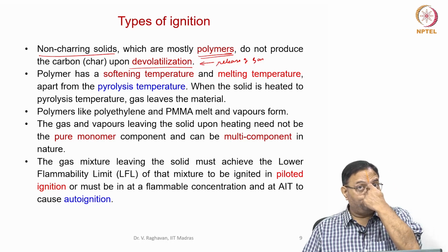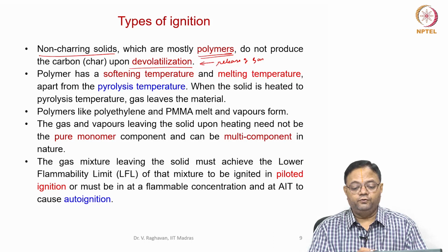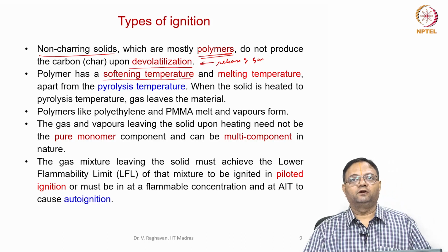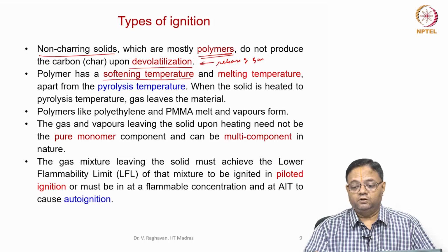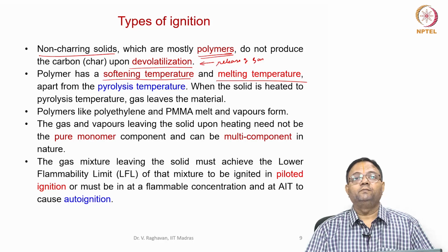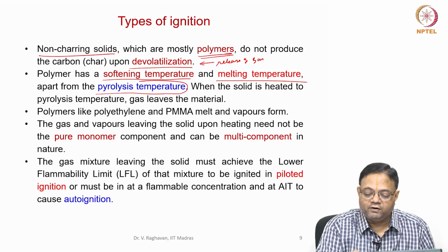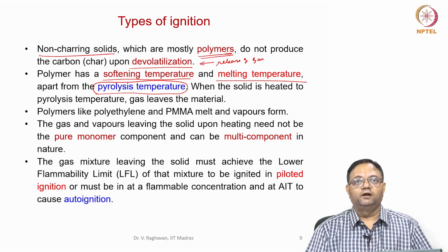Now when you do this heating of the non-charring fuel, there is a temperature called the softening temperature. A rigid plastic can soften. It can melt when it reaches the melting temperature. Now please see that the pyrolysis temperature is the one at which devolatilization takes place, where the gases are released.